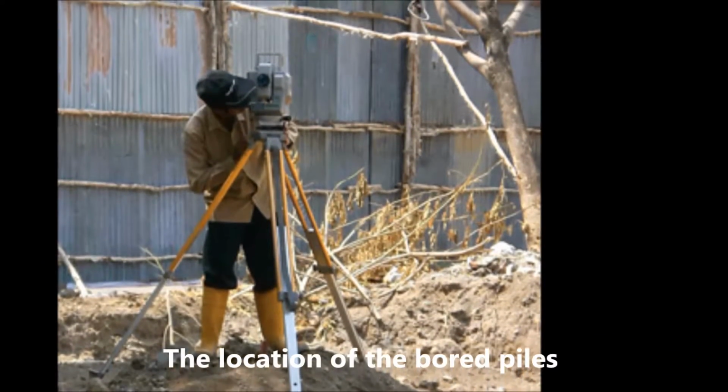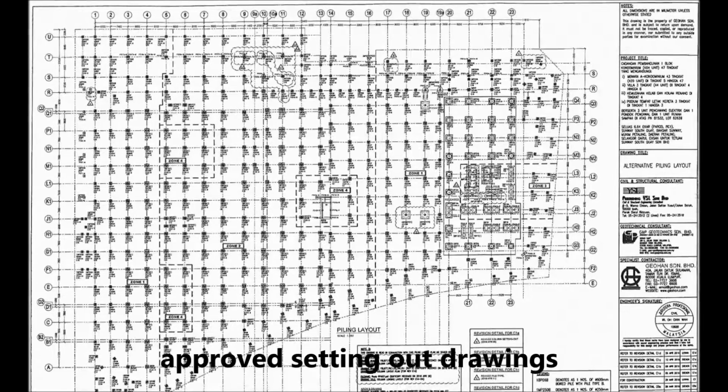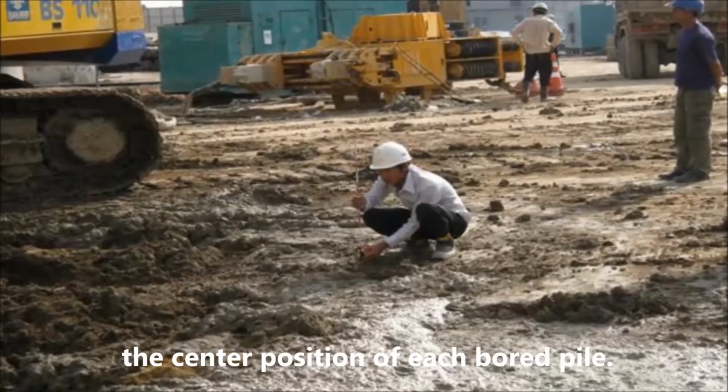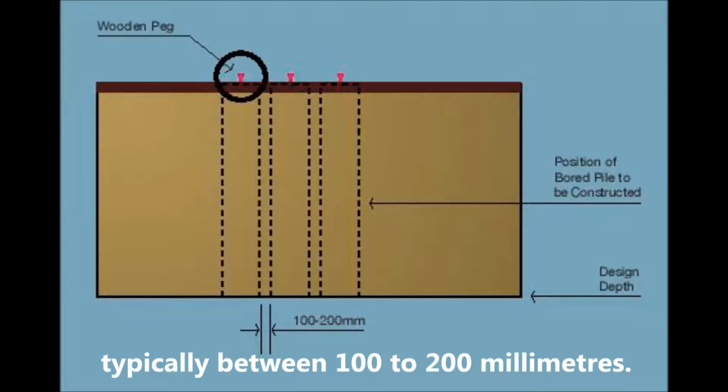The location of the bore piles will be set out and pegged by the land surveyor based on approved setting out drawings from the consultant and control points at site. Wooden pegs are used to mark out the center position of each bore pile. The gap between two bore piles is typically between 100 to 200 mm.